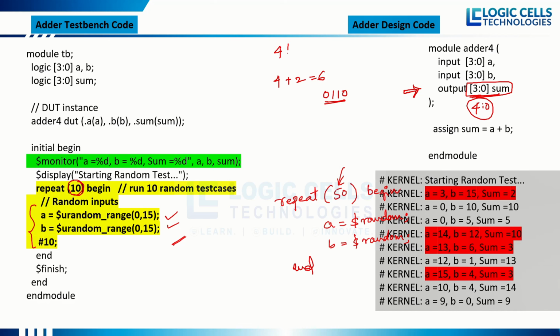If you add 4 plus 6, it may support. It is 10. If you go more than 15 for the sum, it will not support and will not give you the actual result. The 1 bit will be truncated and only 4 bits will be present inside your sum, right? So that's why we need to have 4 down to 0 here. This is the mistake we need to identify by providing bigger values for A and B, correct?